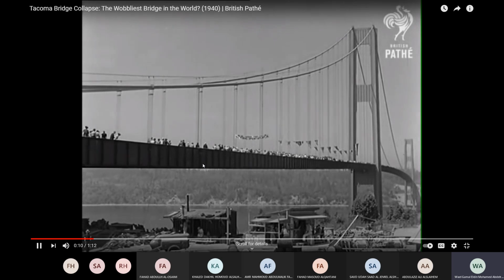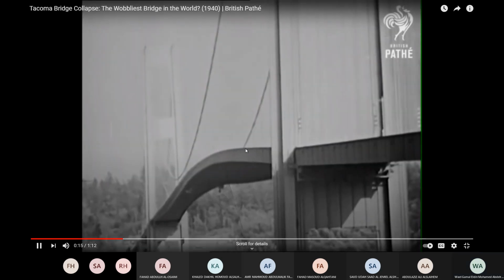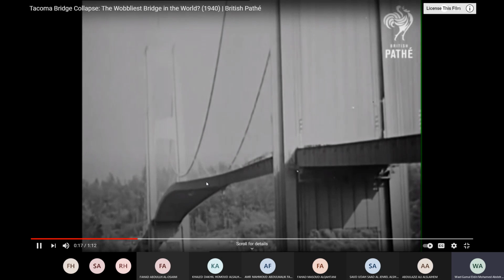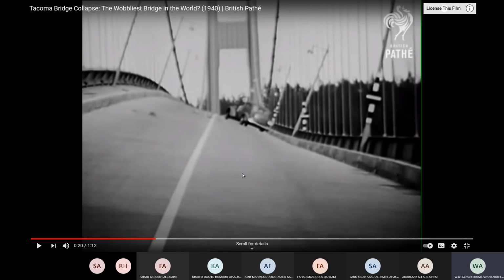See, this is a very strong bridge. You see what happens? You see in here in the middle? That's a bridge, steel and concrete. And it's responding like this because of the wind going right and left, which is a weak wind, but it's exactly at the same natural frequency as that bridge. Okay. And what you are seeing here is what we call the modal shape of that structure. That means how it responds to forces applied with the frequency we're talking about, the natural frequency.